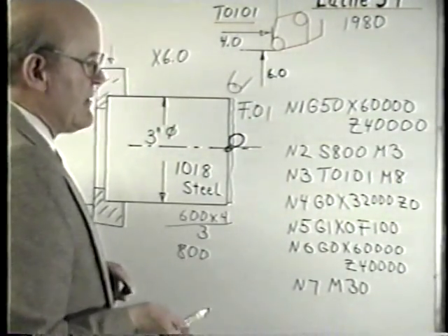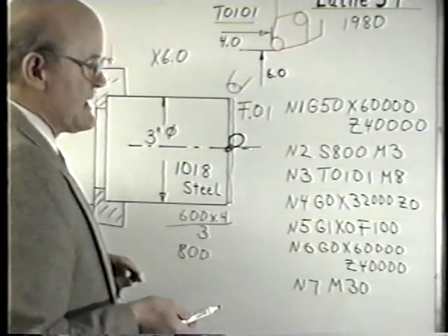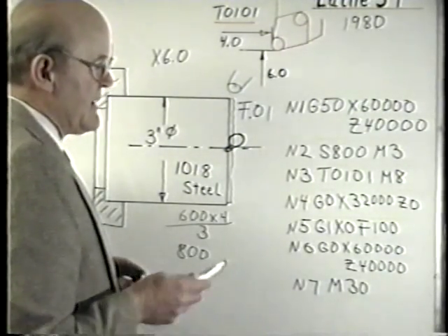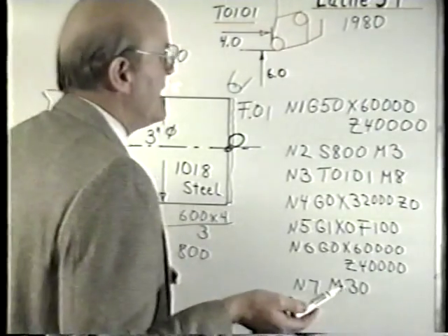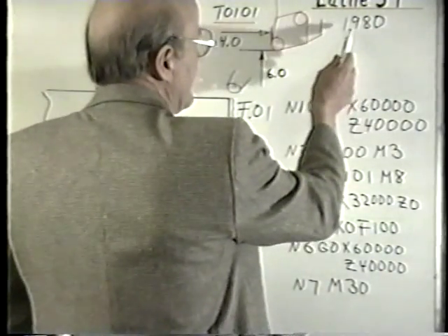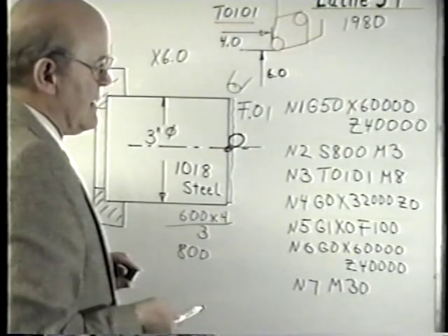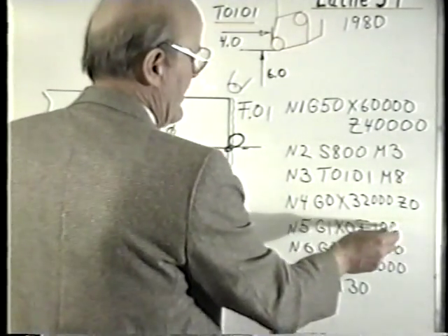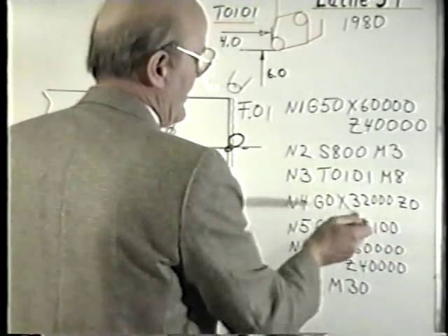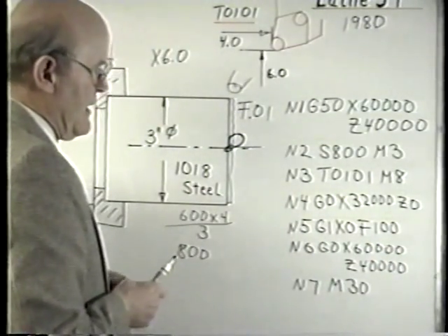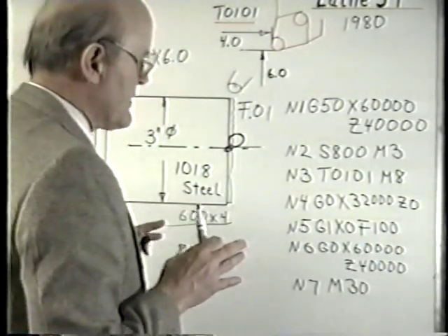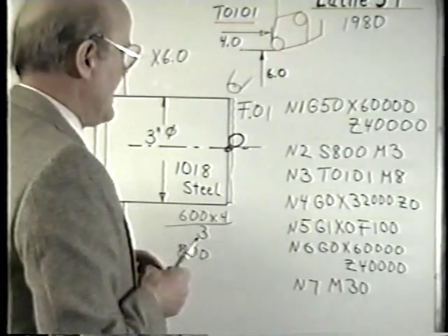It didn't have many of the features. It didn't have nose radius compensation. It did not have constant surface feet until very, very late on a few machines. Feed rates had to be written out longhand, again without a decimal point. But the overall programming procedure was pretty much the same.